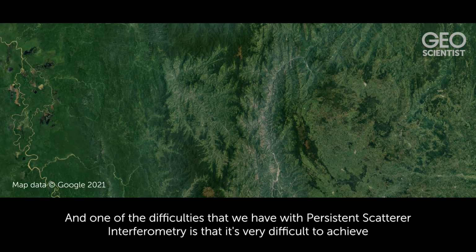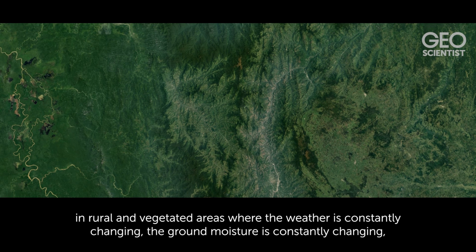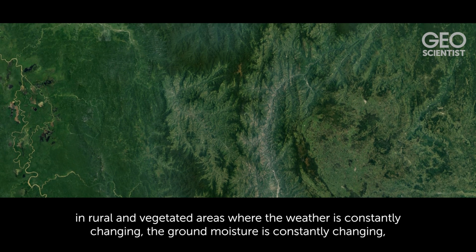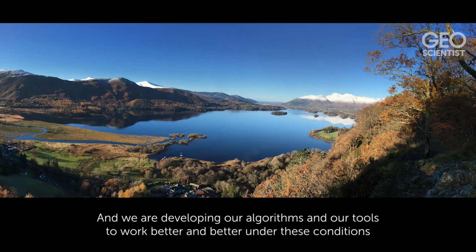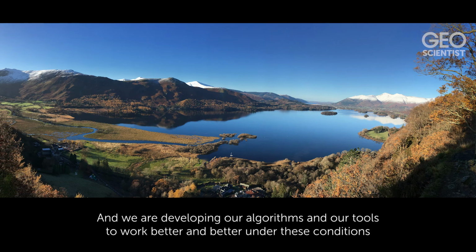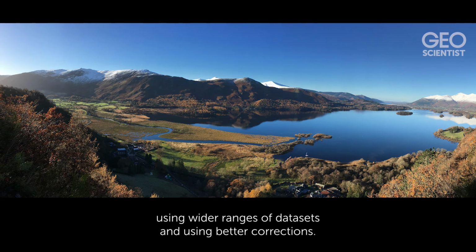Finally, the sorts of techniques that we're applying are evolving all the time. And one of the difficulties that we have with persistent scatterer interferometry is that it's very difficult to achieve in rural and vegetated areas where the weather is constantly changing, the ground moisture is constantly changing, and of course plants are growing. And we are developing our algorithms and our tools to work better and better under these conditions, using wider ranges of data sets and using better corrections.